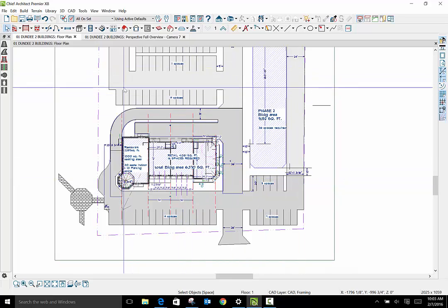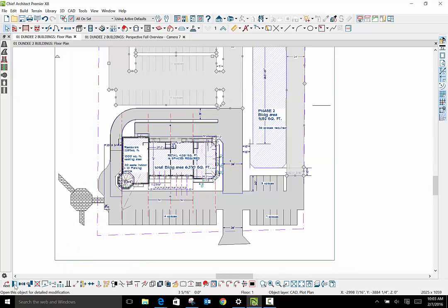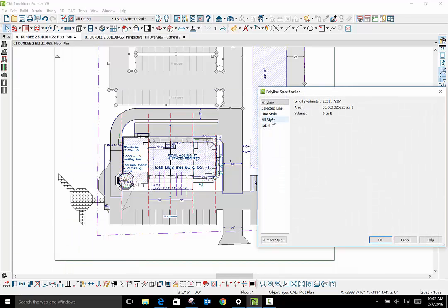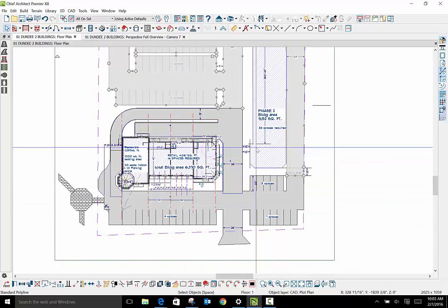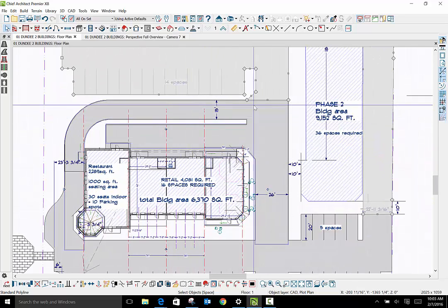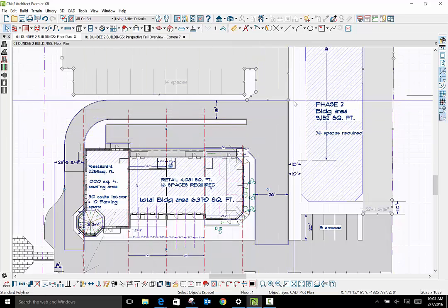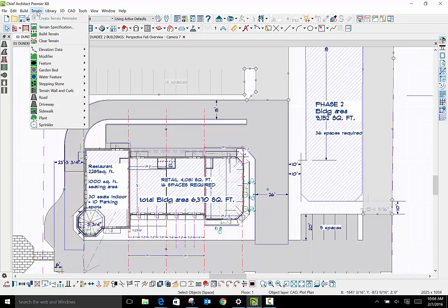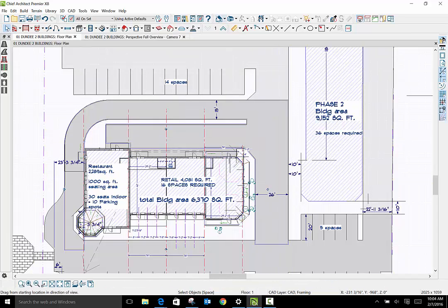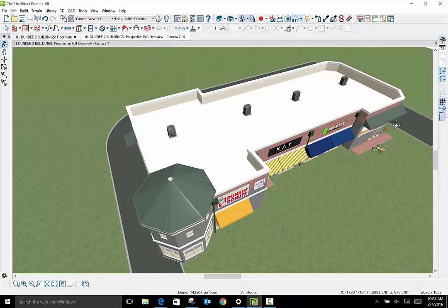So once we have an underlay, for example, this exists on the CAD plot plan. And we are in the process of drawing, overlaying right on the very top of it. We can snap to it. We can draw the curb and gutter roadway, which is this command over here. If you go to terrain, driveway, polyline driveway, that's what we're working on. So we're in the middle of trying to create that right now. We are here. Just got started.